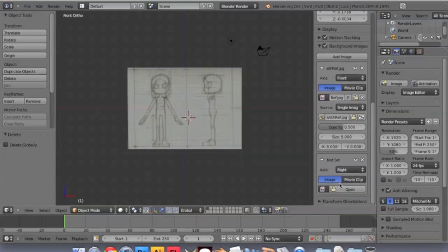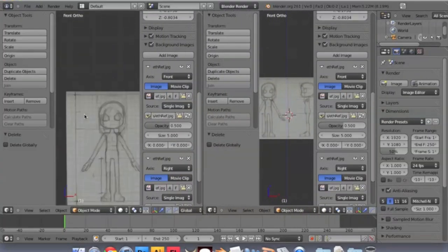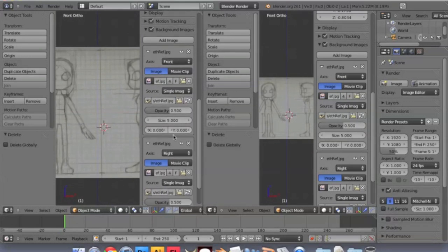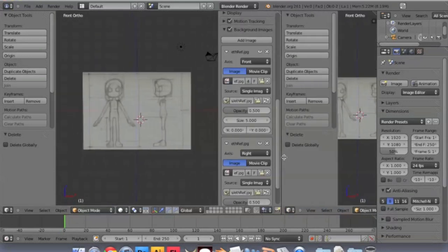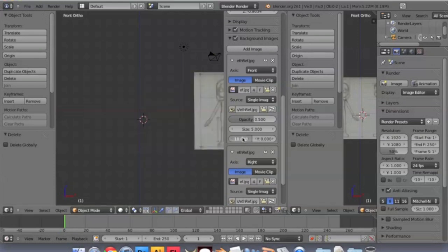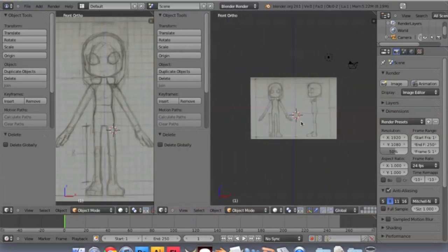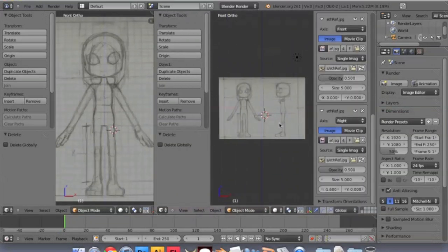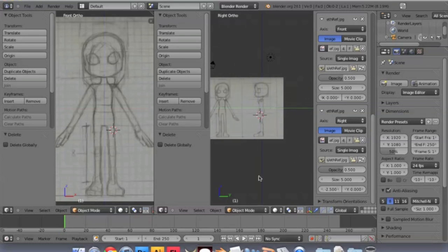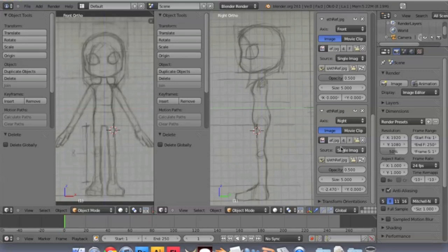You split the screen, set one for Front View and the other for Right View. Now afterwards, you adjust the image. Make sure you're in the front view image, not the right. And same for the other screen, as last time I checked, I wondered why my image was not moving when I tried to adjust it, and I realized I was in right view when I was supposed to be in front. But you get the idea. And make sure on the screens that you actually set the view to front or right, otherwise you won't see it. And make sure they're in orthographic.